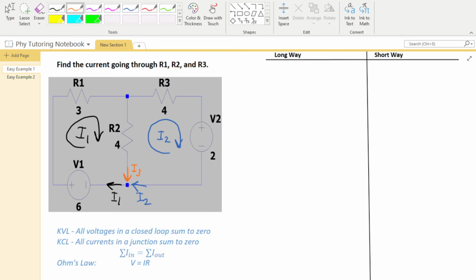That's all that means. And now this is where we use Kirchhoff's current law. The current going into a junction is equal to the current leaving a junction. So I have these two currents entering my junction, then I have I1 leaving my junction. So let's set up this formula. This is my I3 formula, and I'm saying that the sum of the currents entering my junction, I3 plus I2, is going to be equal to I1, the current leaving the junction. Again, right there, we just used KCL. So it's important to remember we made that assumption there. But I just wanted to address that right away.